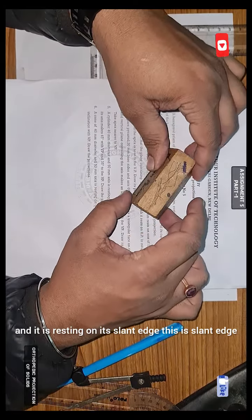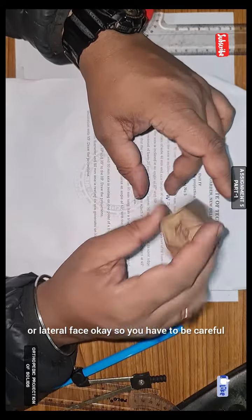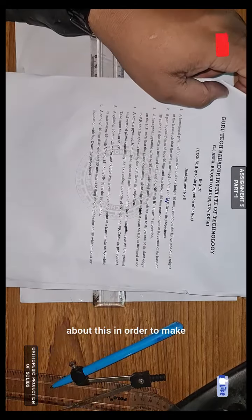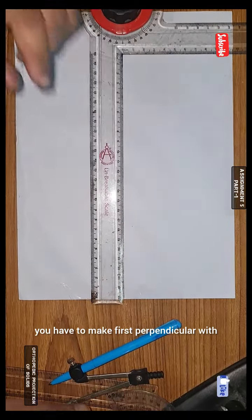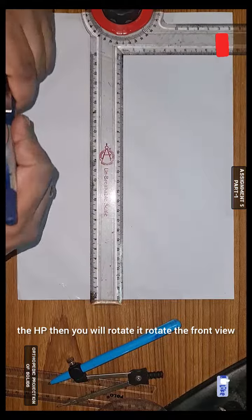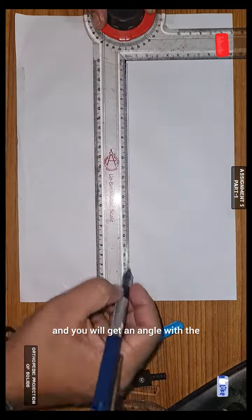This is slant edge and this is slant face or a lateral face. Okay, so you have to be careful about this. In order to make angle with the HP, you have to make first perpendicular with the HP, then you will rotate the front view, and you will get an angle with the HP.